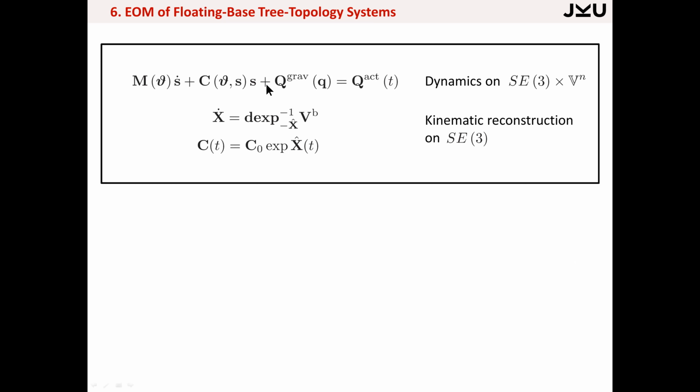So this equation here governs, again, the dynamics, whereas now we have to take care of the kinematics, and that is maybe the mapping that I was alluding to at the beginning. This is the relation with the differential of the exponential, where we get differential equations for x dot. This is the canonical coordinate that goes into the exponential in order to reconstruct, that's why they're called reconstruction equations, to reproduce the motion of the system, because what you get out of this equation is just the velocity, and out of the velocity you get the pose. You see, this is a kind of two-stage formulation.